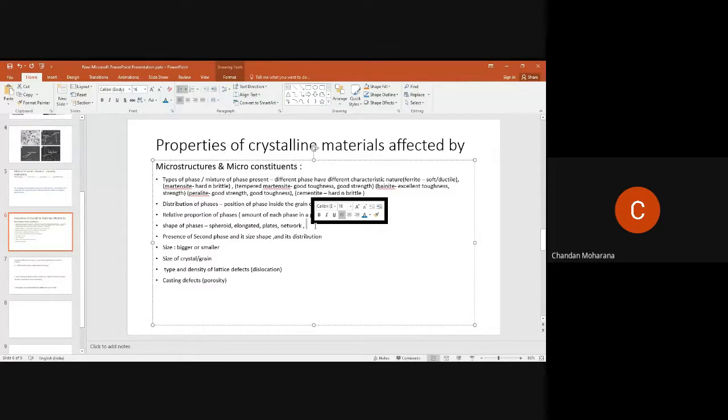So that means if you are taking spheroidized cementite, it is a spherical particle, so the distribution of stress is uniform. You can understand basically. But if you have a plate kind of cementite or a needle-shaped cementite, both ends have sharp ends. That will act as a stress concentration site, or a stress riser. So the stress concentration will be more there, and the crack will initiate from there. You understood now how shape is important, or how shape will decide the properties of a material?